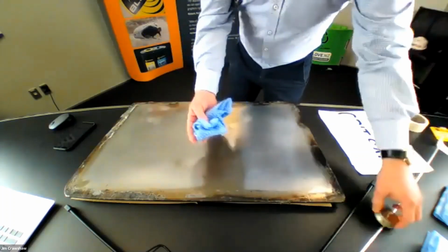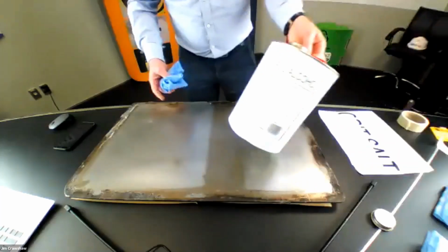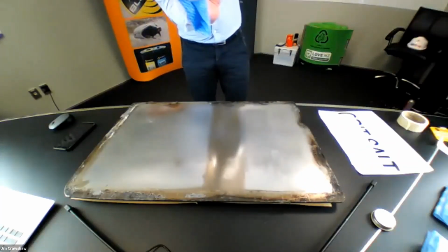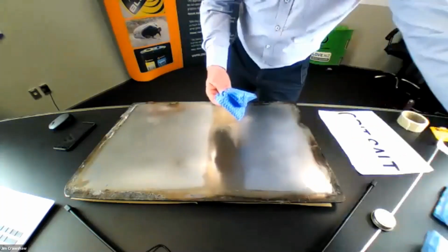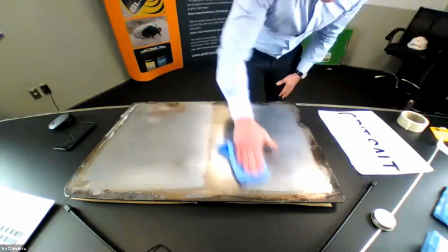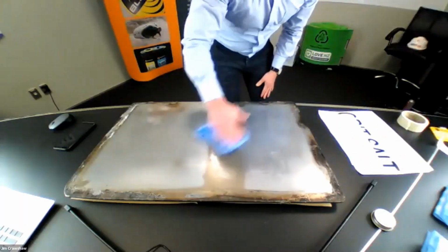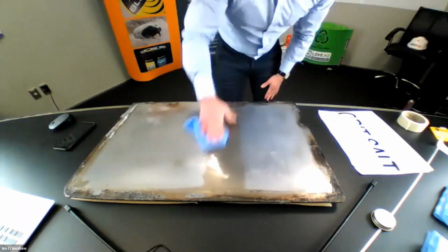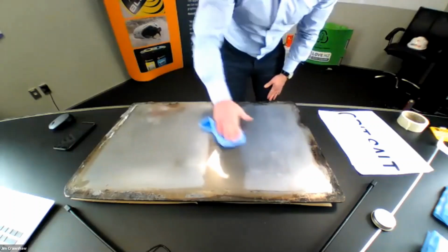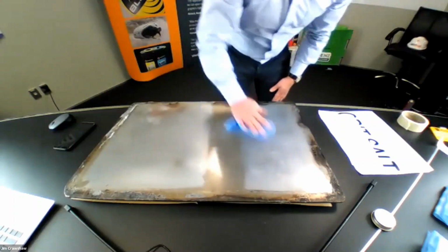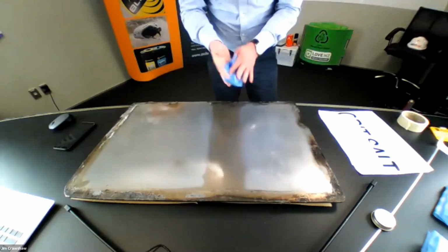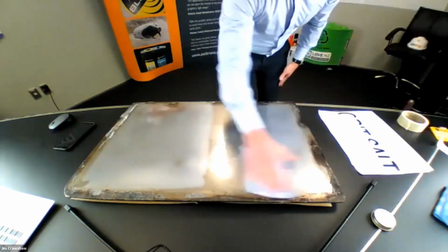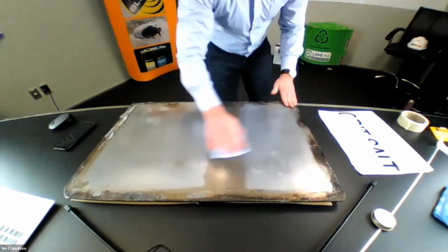So what I'm going to do now is clean this off with a bit of IPA or isopropyl alcohol. You can use your release agent remover, whatever you use, but I find this works really well. I'm going to give this a good clean, a good scrub in the area, and make sure that we've brought all that release agent off. I'm pretty confident we've got most of it there. And I'm going to use another dry rag just to make sure our surface is nice and dry.